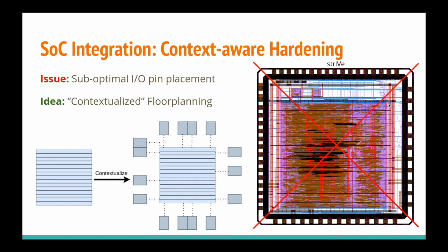And we have only 5 usable metal layers on the top level, so this would surely cause congestion and many problems. But again, the issue is that the tools work bottom-up, not top-down, and that knowledge of how a macro connects externally is not available while hardening such a macro.